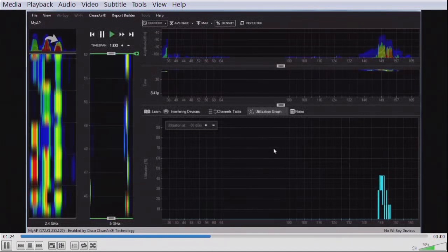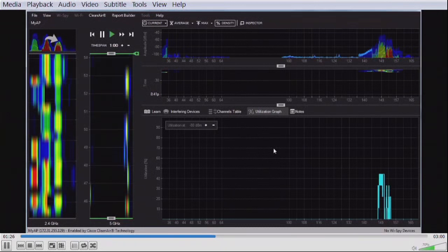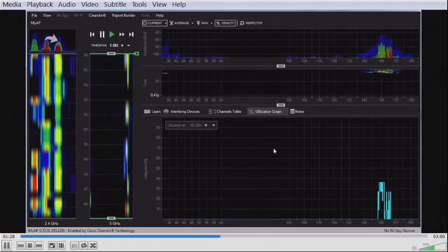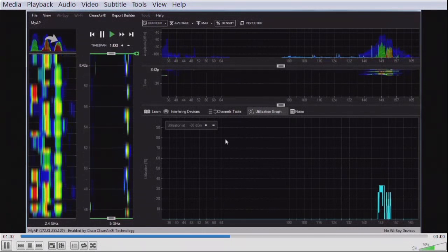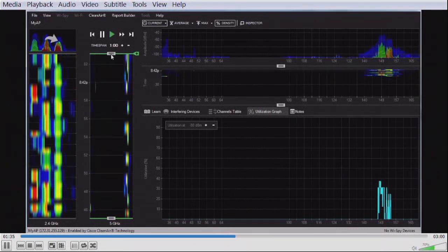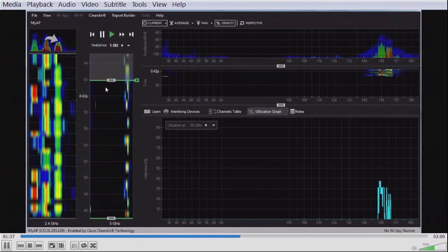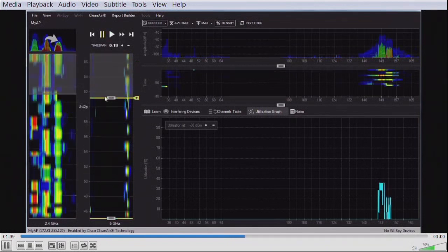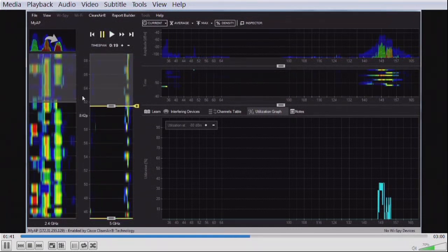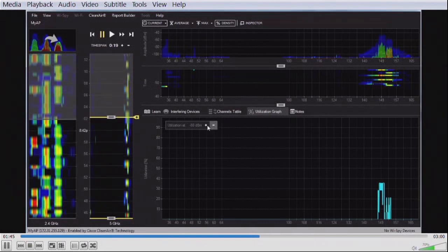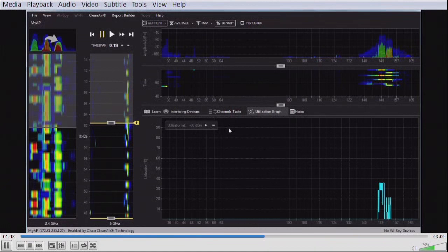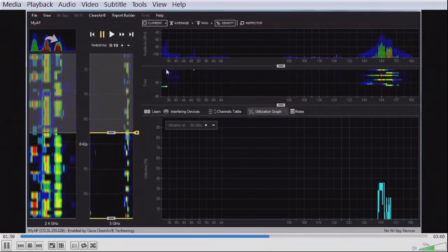And then here on the left side, you see a live feed of the RF energy that is being detected in all these different channels. And on the top, you can see the activity on those channels. The purpose is not to see the 802.11 traffic, the 802.11 activity, but have a raw view of what kind of RF energy you're detecting in any of those channels you're working on.